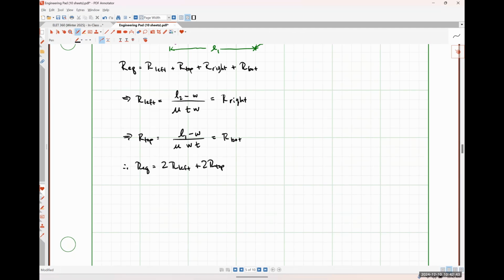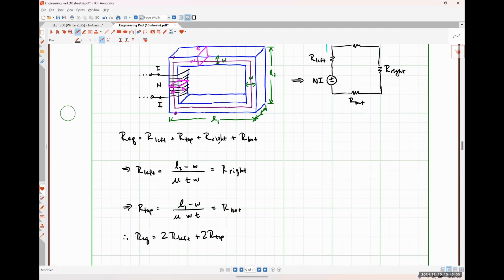But we can actually notice something else here as well if we were paying enough attention, okay? This will not be true for all cases, but it'll be true for a lot of them: the cross-sectional area of our core never changed, right? So realistically, we could have just done the length of the average flux path as one big thing, and then the cross-sectional area as one computation, right?